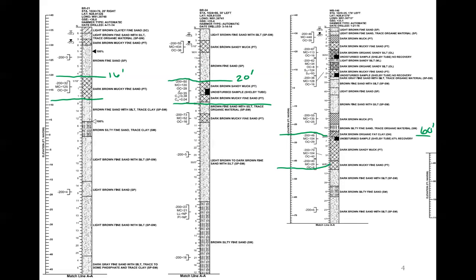So as we mentioned before, organics are a big headache. And if they're at the surface, we usually just remove them entirely. But 60 feet down, how are we going to remove this soil layer? We can't dig a 60-foot excavation and then suck them out. So what we actually do is use this delta sigma Z, this increase of stress, to our advantage.